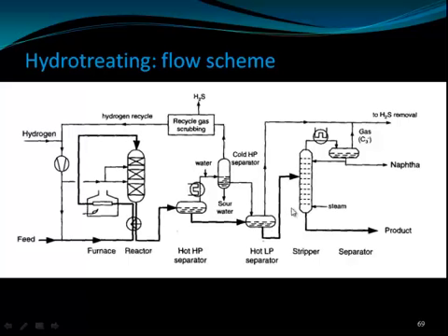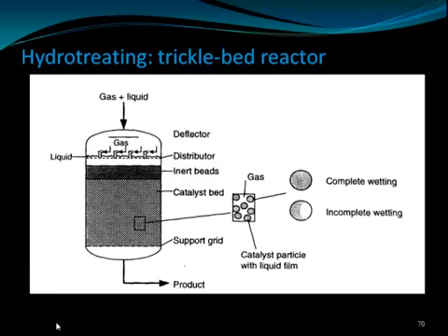Then from the low pressure separator, it is sent to the stripper. In the stripper, the sulfur is removed. Then we get the desulfurized product over here, and the other fractions that are C3 and more. We get C3 components as gas, and we can separate naphtha, which has a higher boiling fraction, and the remaining gas we can send for further sulfur recovery. So here, treating with hydrogen removes the sulfur, and then it is sent on to give the products of the desulfurized crude oil.